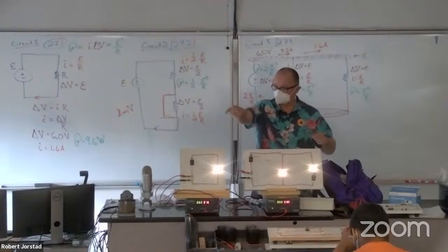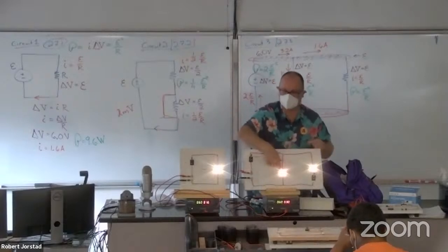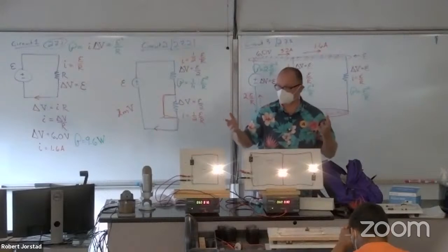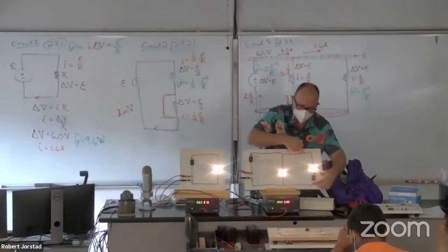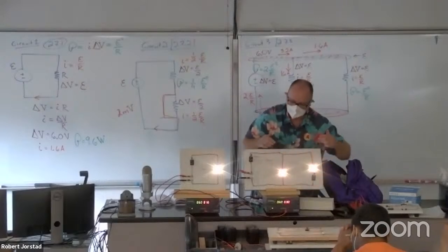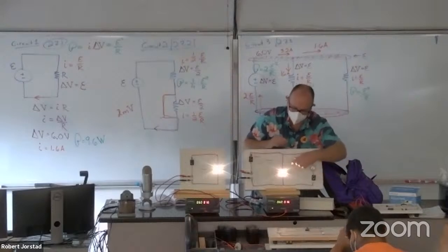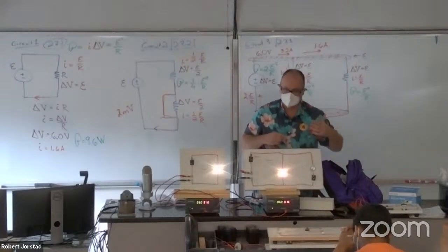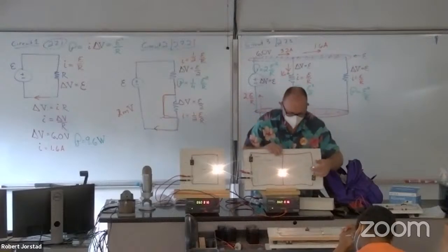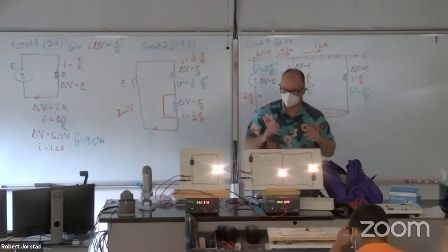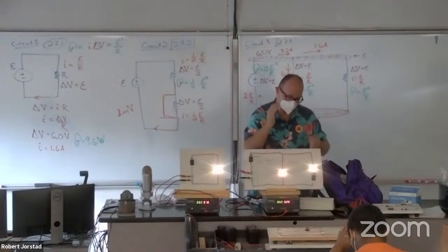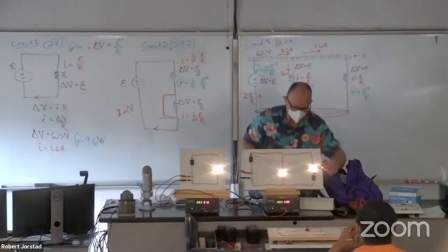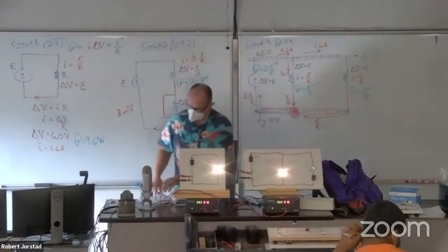As we have seen, and perhaps you've seen this in real life, that barely noticeable flicker is there, and you've probably seen this in your house if you turn on a vacuum cleaner or something with a big motor in it. Strictly speaking, there's a tiny bit of resistance in these wires too, right? When I change this by opening the circuit, I'm not only taking out this light bulb, but also all of this, and so the circuit's changing a little bit. These wires are not completely negligible, but they're probably negligible to at least the second decimal. That's what you're noticing there. We can see it with our eye, but if you put a meter on there, it's pretty low. All right, ready for the next one?